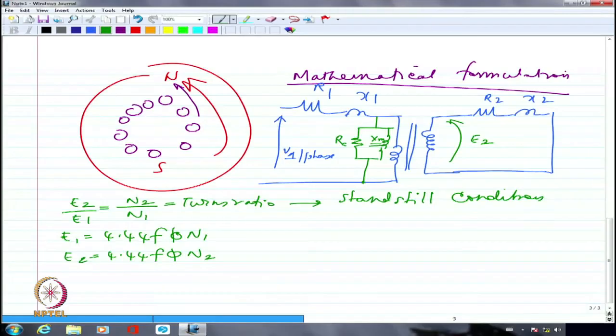So it is basically a pretty involved design as far as the squirrel cage is concerned, although it looks very simple. But the turns ratio in squirrel cage is not a straightforward one. It is a very straightforward one in the slip ring rotor. It's pretty simple. Whereas in the squirrel cage, I have to calculate the equivalence in terms of currents and torque and everything. From the torque, I will decide what is the current. From the current, I'll decide what is ultimately the turns ratio. Right? From the primary current to the secondary current. That is how we do it normally.